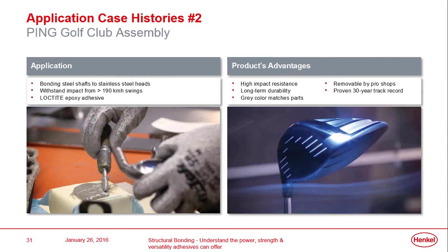Ping, the golf club manufacturers, have been using a structural adhesive for over 20 years. In this instance, they need a material which has got significant force transmission, they need high strength, they need toughness, and they achieve that by using a two-part epoxy.